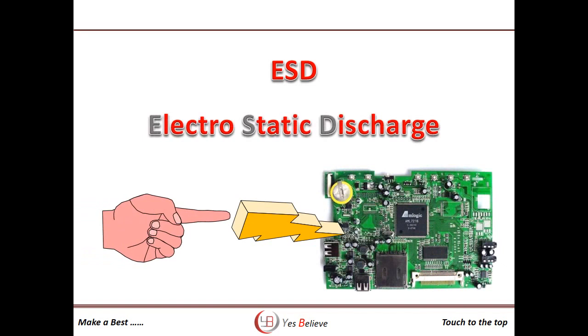You have also seen in any audit, the auditors always focus on the ESD. This might be because they don't know the SMT process in detail or any other reason, but due to this, unnecessary investment on the SMT shop floor is done for ESD control. But my experience says if you have made the basic precautions for ESD at your workplace, then there is no need of making an extra investment, as the component failure due to the ESD is very rare.